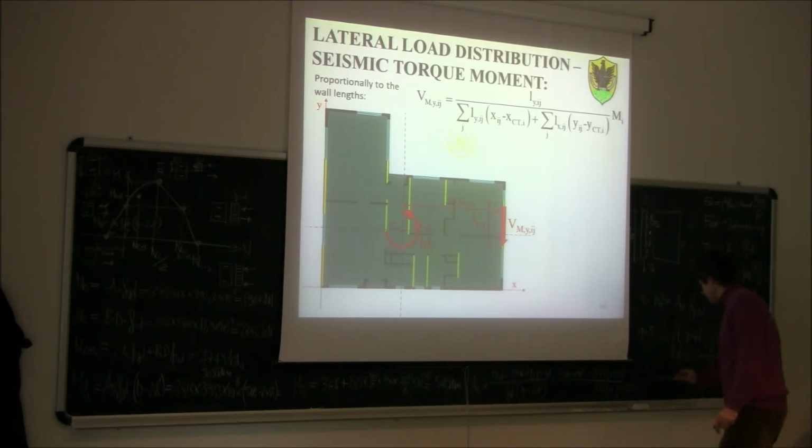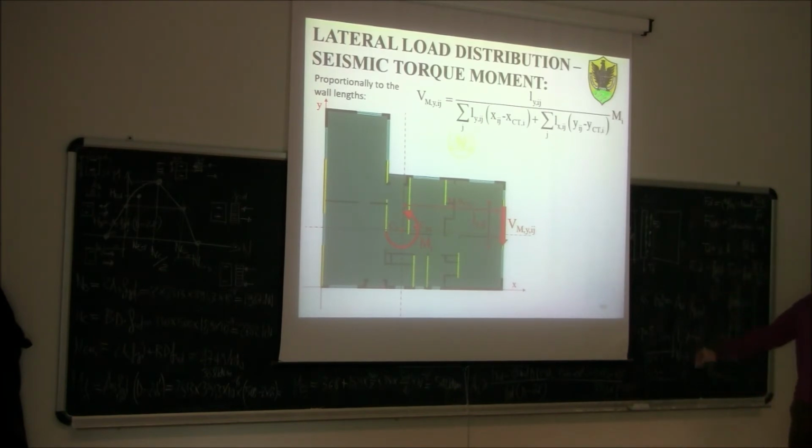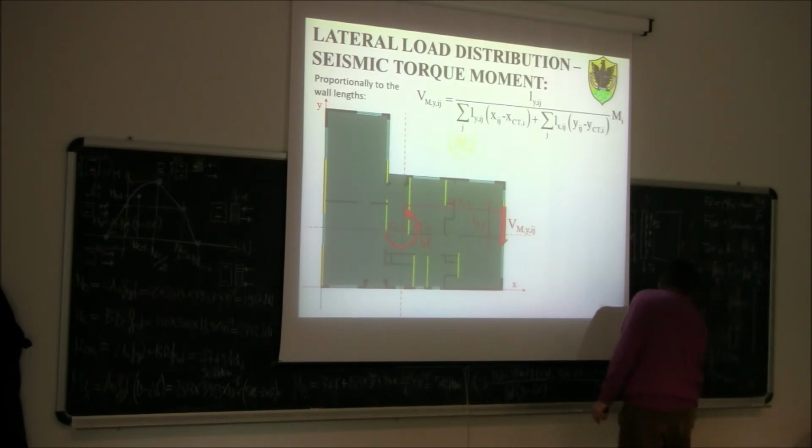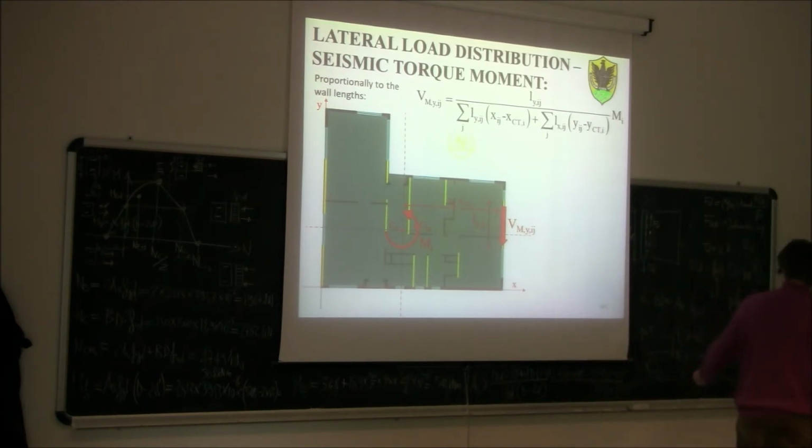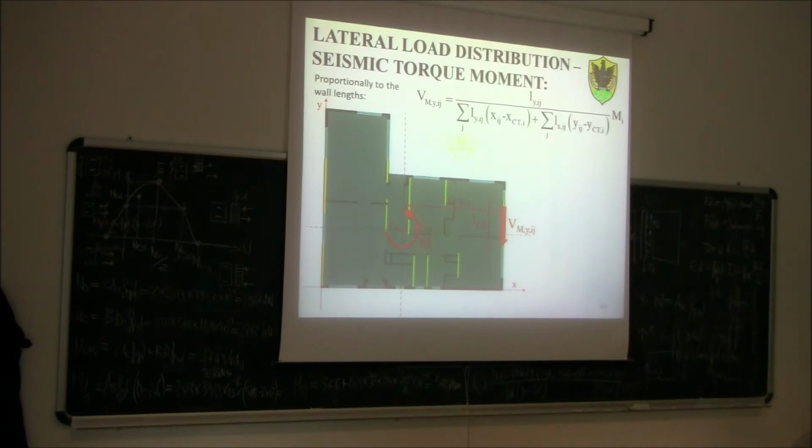If you go back to see, for example, remember you have a connection like this with a number of bolts, and we had a bending moment for the beam, which was a torque moment for this connection. We derived some formula to calculate the value of this force, the shear force in the bolt connection. And those formulas you can see here, they are very similar. The only difference being that in this case, the bolts are different, they're not the same size like that.